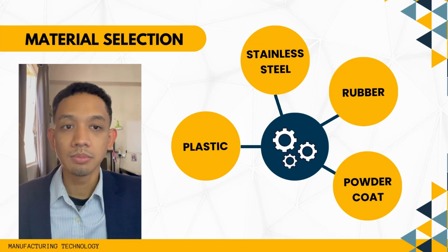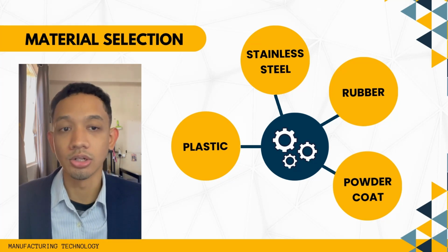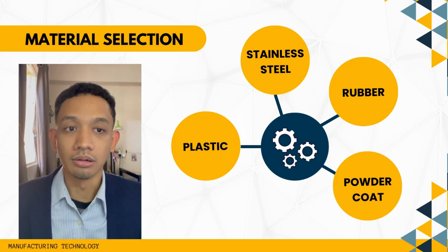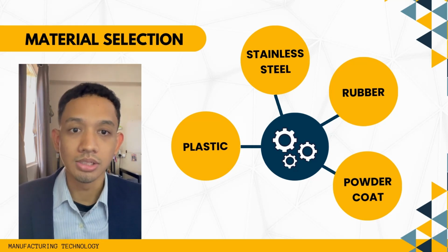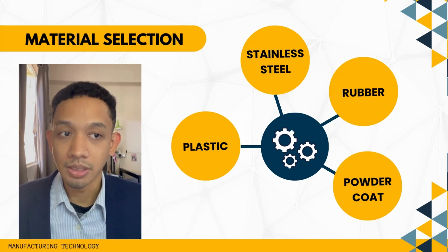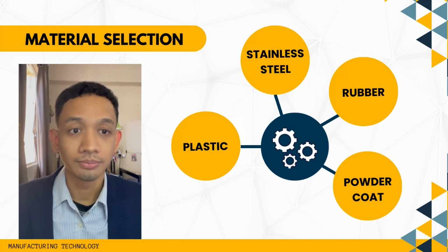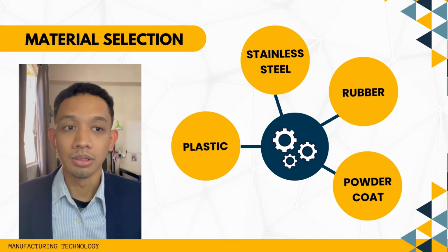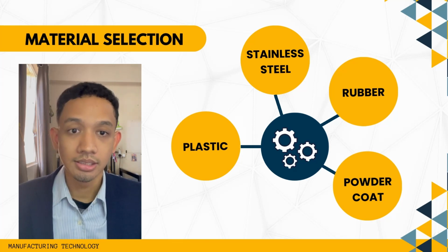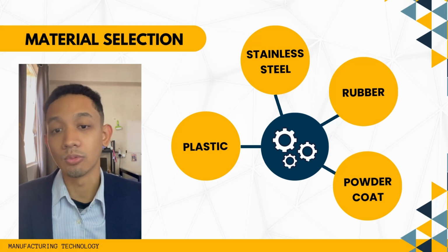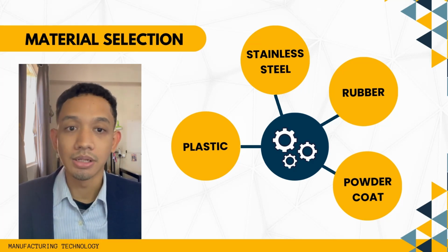So the MCB box has rubber attached on the corner of its door. The rubber plays a role as the box seal. The rubber is used to create a tight seal when closing the MCB box door, and rubber can act as a vibration dampener, keeping the components inside the box safe and secure. And not only that, but rubber is also weather resistant, and the invasion of water inside the box can be prevented while simultaneously keeping the components safe from water damages.